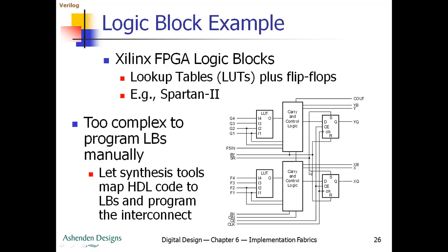Similarly, the second LUT can also implement functions having 4 variables, F1, F2, F3, and F4. The working of the carry and control logic is the same as we have discussed in the previous discussion.